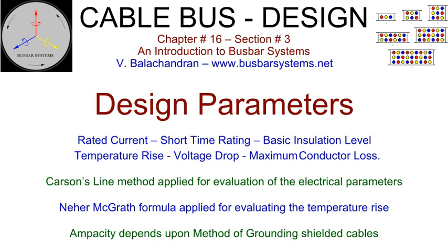Cable bus manufacturers work closely with the cable manufacturers for the data on cable and envisaged temperature rise under various service conditions. In a three-phase short circuit, the forces experienced by the conductor depends upon the magnitude and direction of the currents and distance between the conductors.